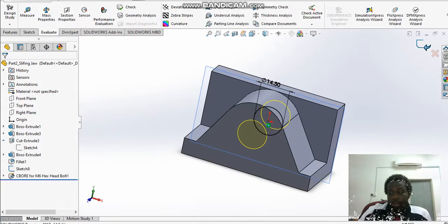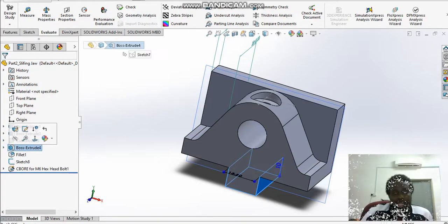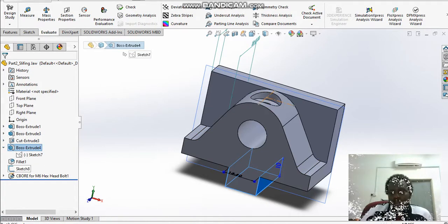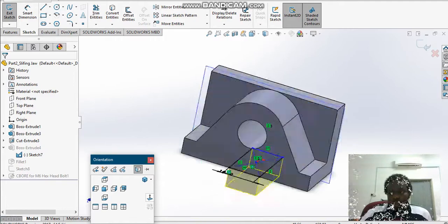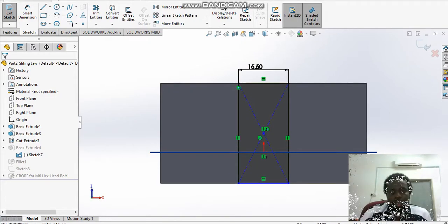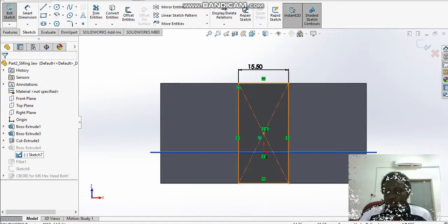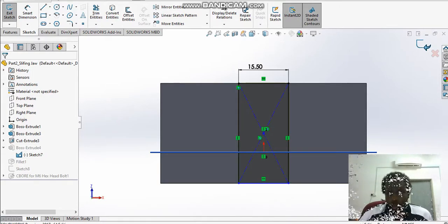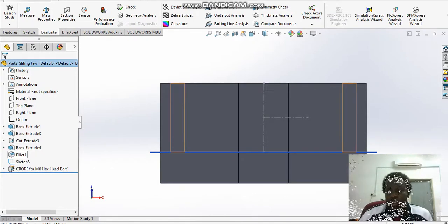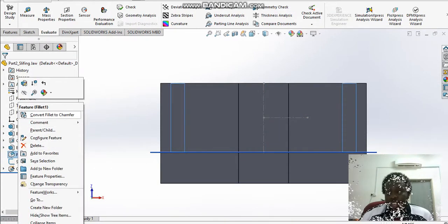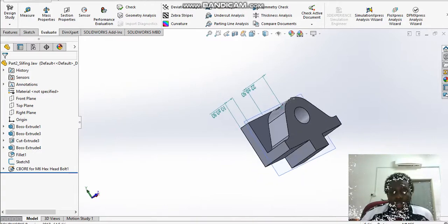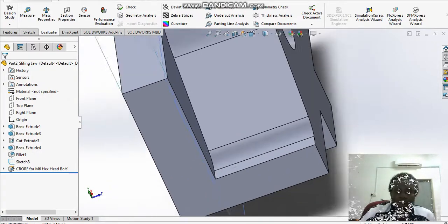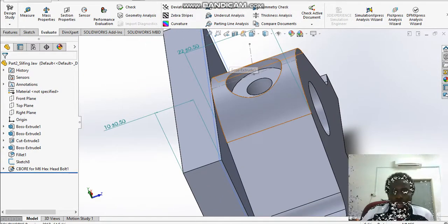For part 4, you just adjust one button from the rectangle to extrude 10 mm. While we're using this one, use the fixture from the left side. So he just asks us to use the blind and follow the instruction at the same time. For step 5, we make the fillet option. The fillet option only asks us to do 5.0 mm. So we make a similar object, and then we make it from the upper side, then make the hole as we conclude.